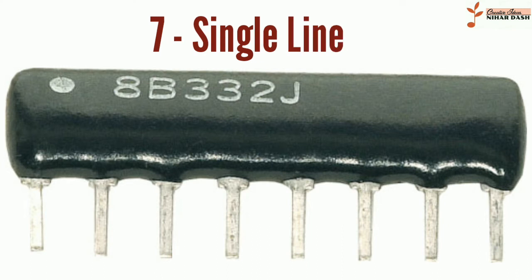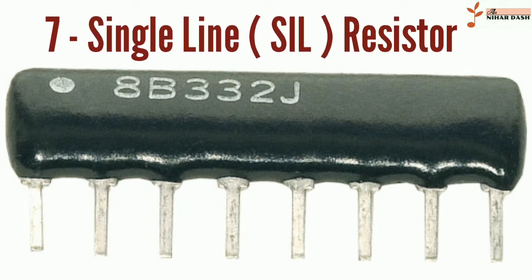A single in-line, SIL, resistor package with 8 individual 47 ohm resistors. This package is also known as a SIP9. One end of each resistor is connected to a common pin. Series connection is useful to control the current in a circuit. Short circuit in an electronic appliance can be prevented by connecting a fuse in series with the mains, as well as the electronic appliance.